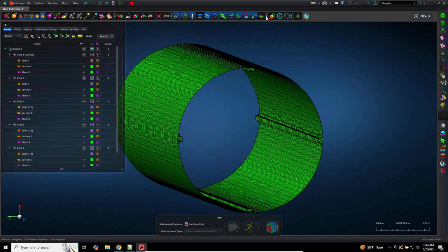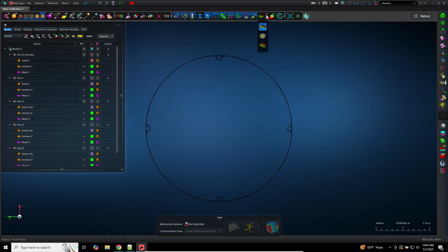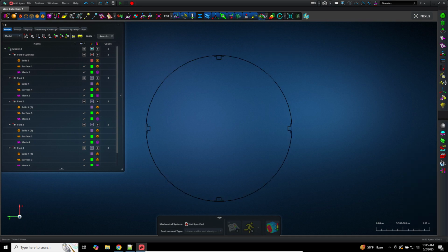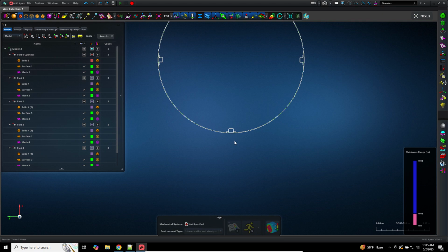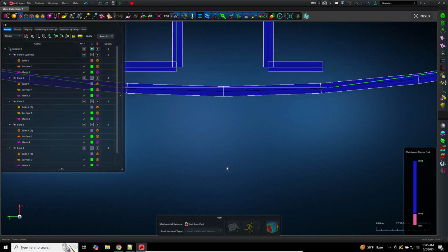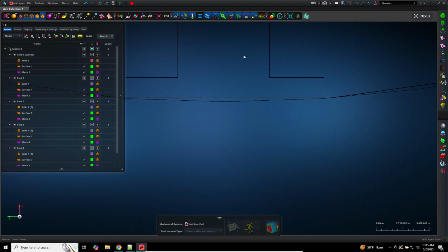Okay, now maybe you want to look at the thickness. What does the thickness look like? Here in this horizontal bar of options, click on this option here. Click on this arrow, click on the 3D option, and then turn it off and on. And then if you zoom in, you get a preview of the thickness for the 2D elements. Now, you can adjust this thickness. It's really up to you. Just know that that's available in this tool.